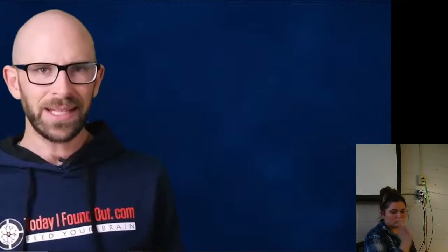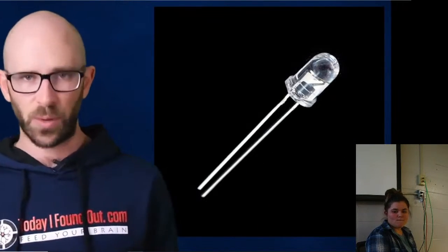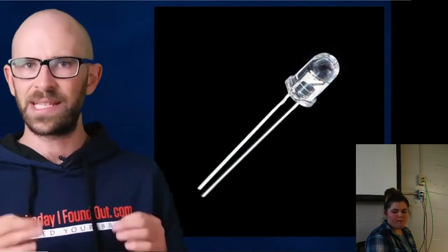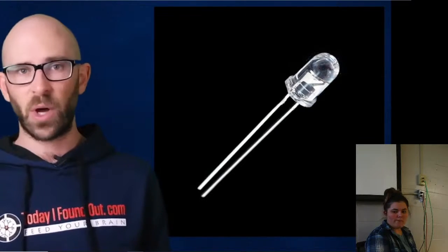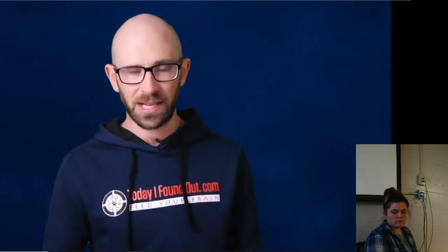In LEDs, the light that ends up being created depends on the material being used and the current that runs through it. In a standard diode, the atoms are arranged so that the electron drop in energy is very small, and thus the frequency of light given off is invisible to our eyes; rather, it is infrared. So simply put, LEDs where you can see the lights are made of semiconductor materials that create a bigger drop in the electron's orbit so that the frequency of the photon packet comes out in the human visible spectrum. They can even be designed so that the amount of electricity flowing through them will actually change the drop, and so you can have a multicolour LED.